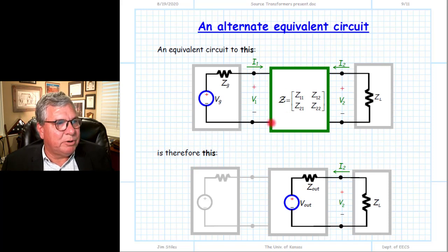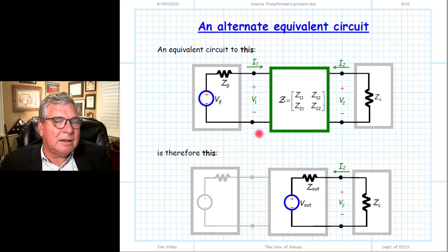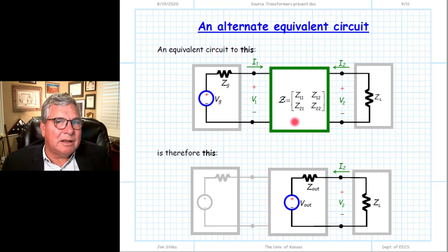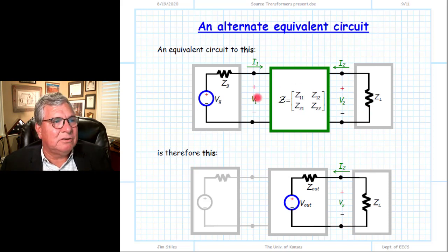And once we have that new input impedance, then we have a very simple source connected to load, and we can determine current, voltage, power, and so forth. Moreover, I've stated that the transformation that is completed from ZL into a new value Zin will tell us something about that two-port device, and we'll get to those results later, what it tells us. But it's a very important aspect in microwave engineering, radio engineering, this idea of an impedance transformation.